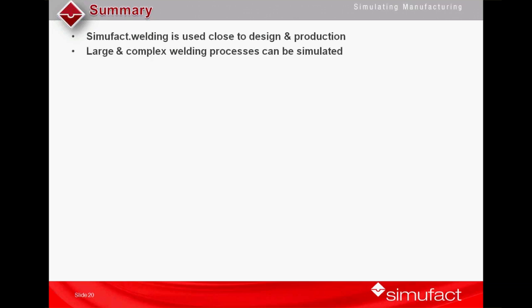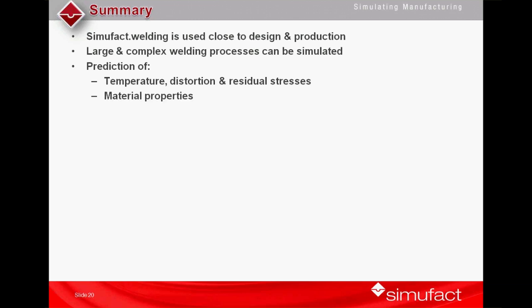So in summary, before we go on with the live demonstration, what I wanted to explain to you is that Simufact welding is used close to design and production. You can simulate large and complex welding processes, and it's used for prediction of temperature, distortion, residual stresses, looking at the effect of material properties, things like martensitic hardening, and then you can look at the structural response to loading after welding.